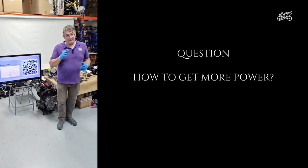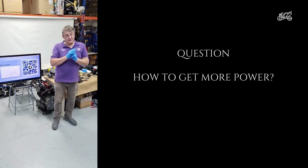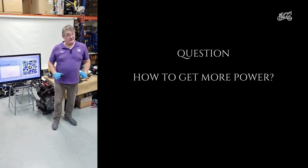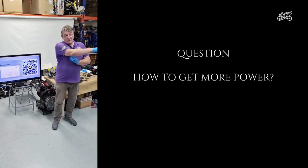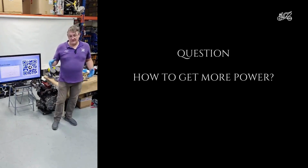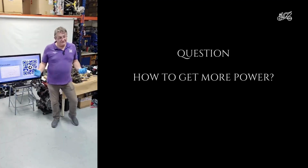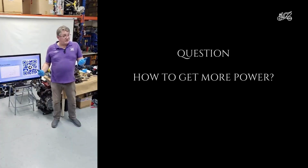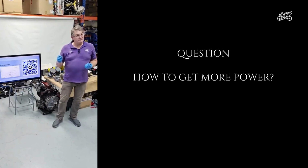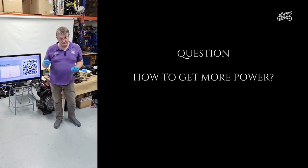So if the ignition occurs later in the cycle, less energy is pushing the piston down, and more of it is just burning on the way out, and that means the engine runs hotter. So if your car's running hot, I would check mixture, check timing, right? Advance the timing, it will run cooler. Richen the mixture up, it will run cooler.